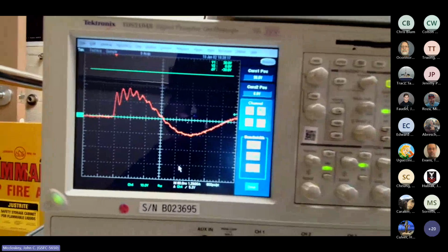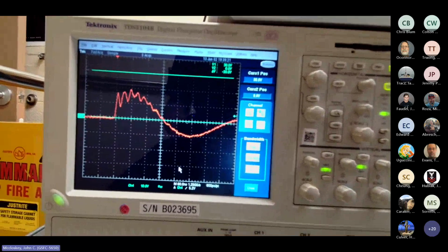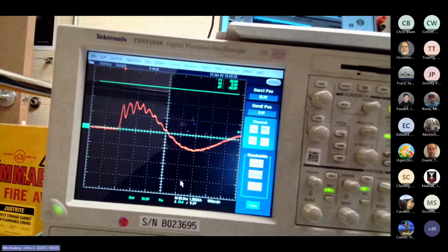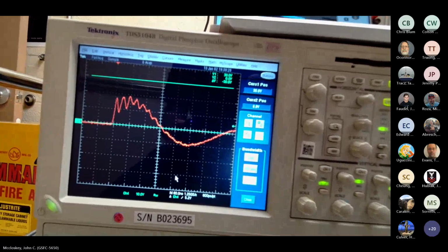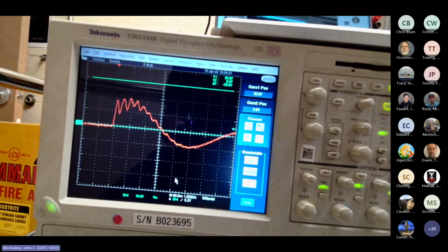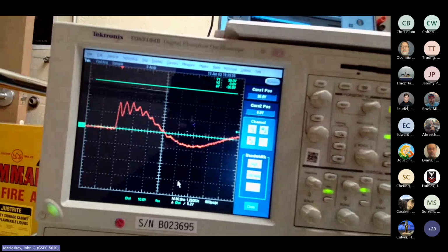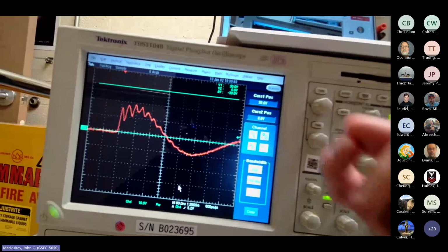Sometimes there is a specific reason, like if you've got a lot of high frequency broadband white noise and you're trying to look at a sinusoid or some signal that's very close to the noise floor. Reducing the bandwidth, if it's not affecting the signal of concern, can filter out some of that noise and give you a better read.